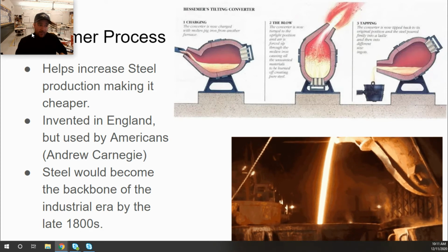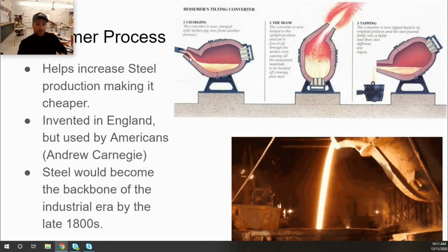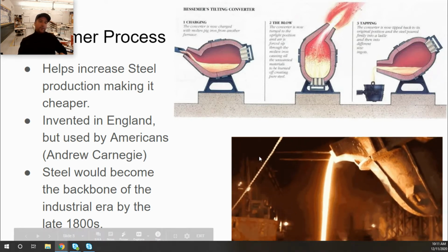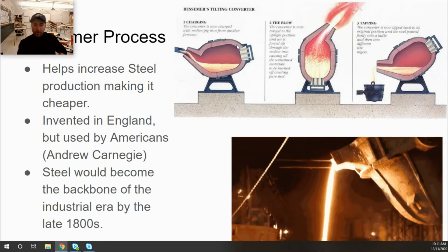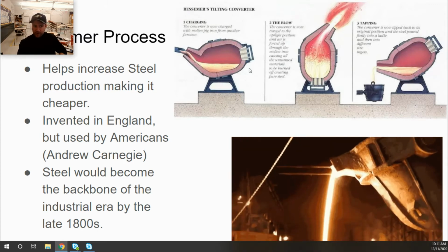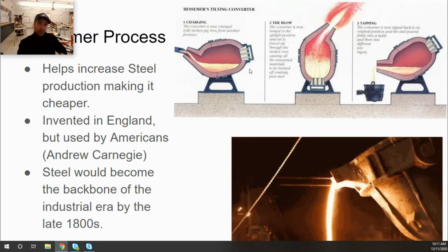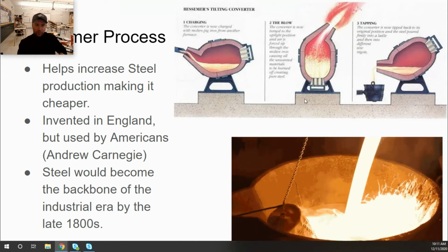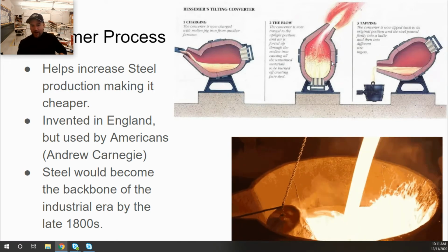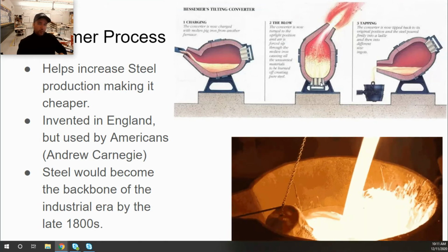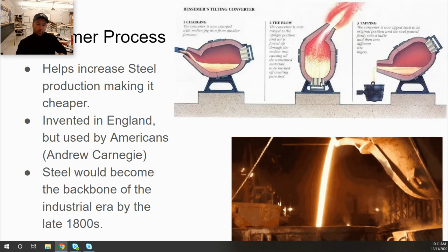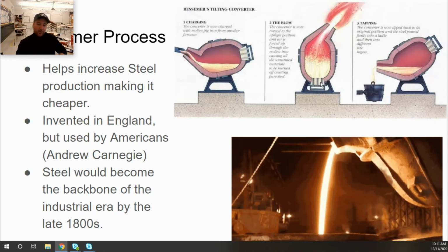But steel doesn't. And so how this Bessemer process works, and if you're staring at this whole GIF, I understand, but bear with me for a minute, okay? You put the raw materials into this giant furnace. You need pig iron, lime and other things. When you tilt it up, you blast hot air into here, which leads it to be really, really hot. That would burn off any impurities that would cause rusting in iron and so forth.